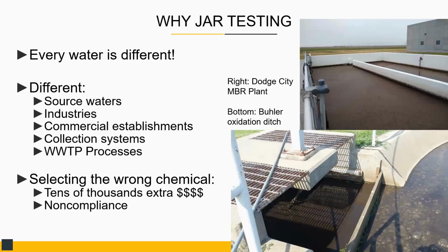If you are looking at chemicals, definitely look at jar testing. I've done jar tests for a lot of facilities, I think maybe 35-ish here in the state. If you've come on since then or have lost it, I do have all of those reports. I can share them with you. Keeping in mind that, if you had significant changes in your collection system, the results may not be very valid anymore. But you do want to jar test if you're looking at using chemicals.